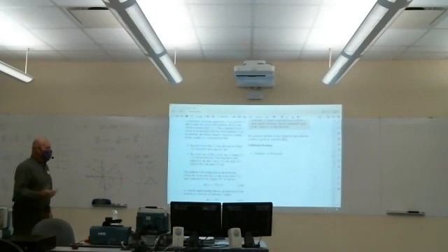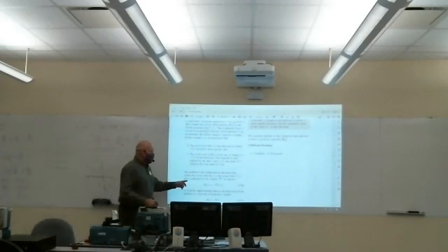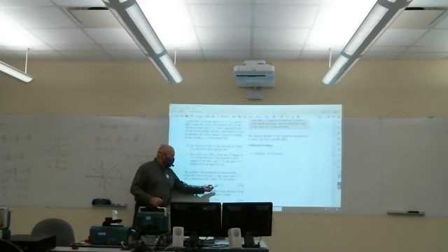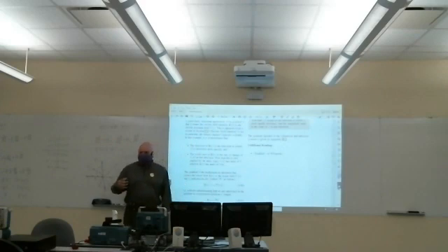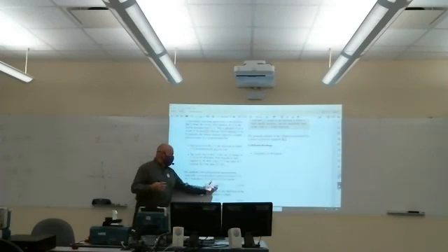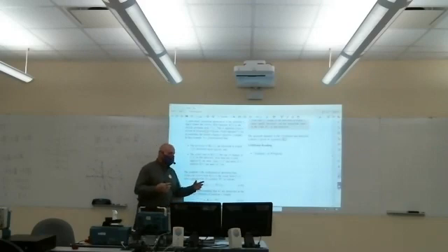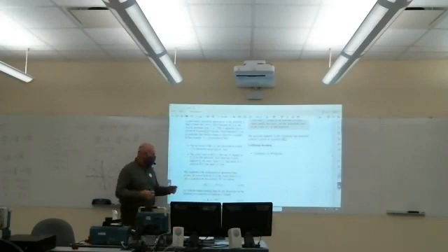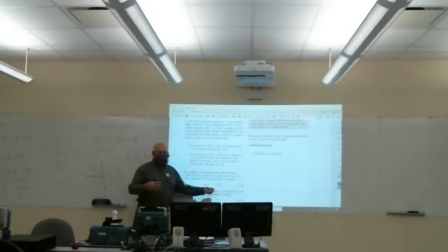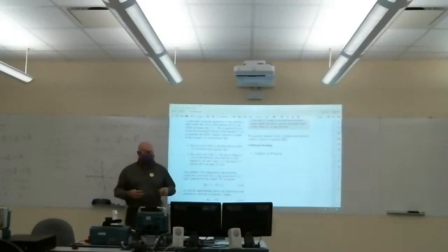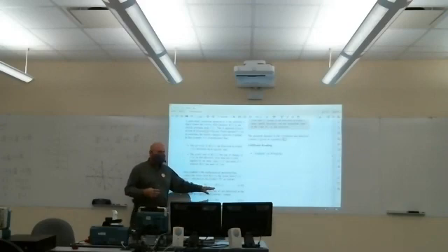Well, our big application in electromagnetics is the electric field. Here, R is not our coordinate in spherical coordinates. R here is just a position vector, so it could be x, y, z, could be rho, phi, z, could be r, theta, z. But the electric field is not the gradient of the voltage, it's the negative of the gradient. So the electric field actually points in the direction of maximum rate of decrease of voltage. But we'll see this in the next chapter when we talk about electrostatics.